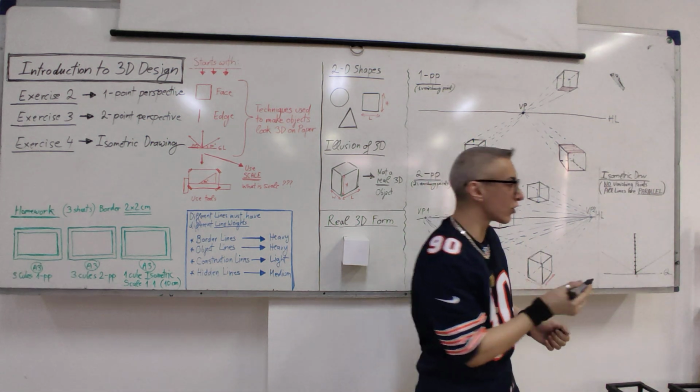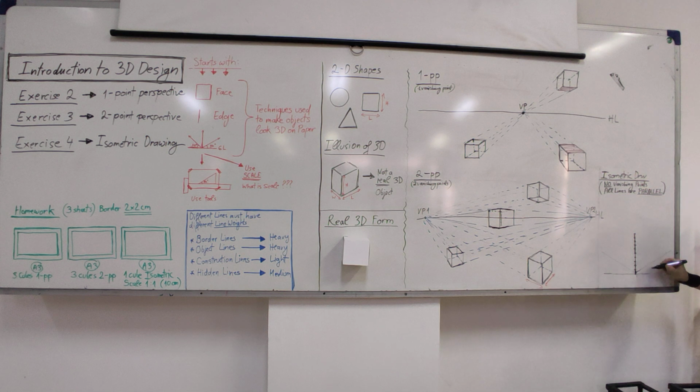So in isometric drawing, this is 30 degree, and this 30. There is another type where here is 45, here is 45, okay? But we will not use it. This is better now, okay? So focus on this. Always 30, 30. From here, this is the first edge with a specific measurement.